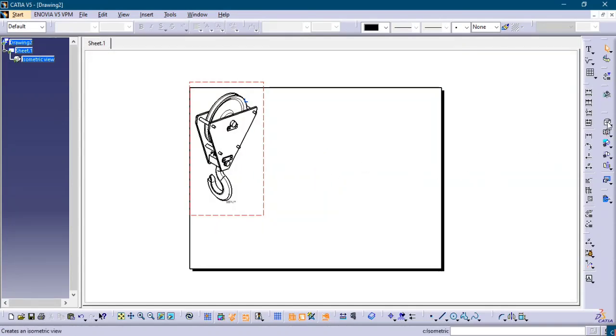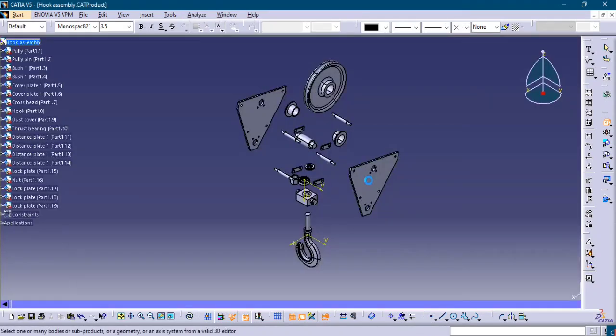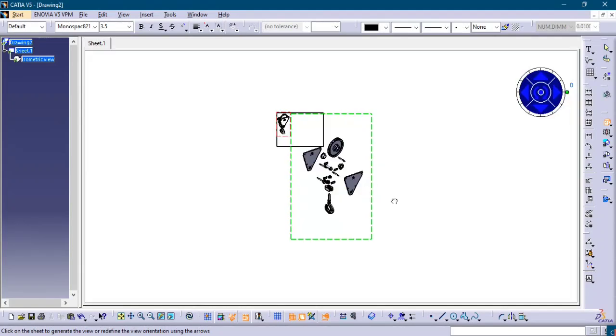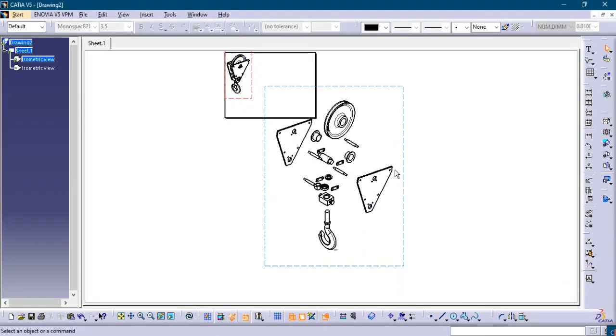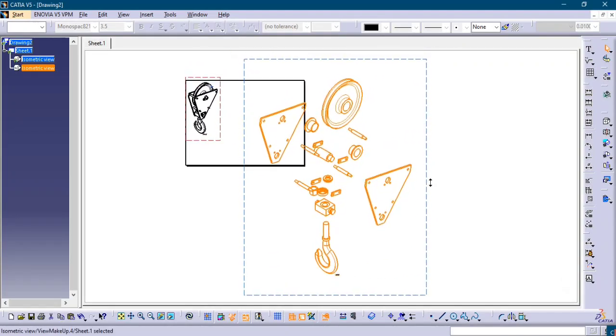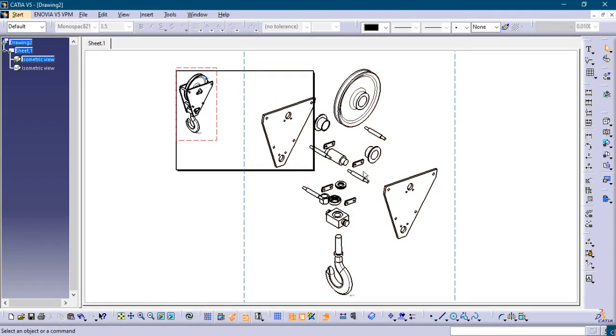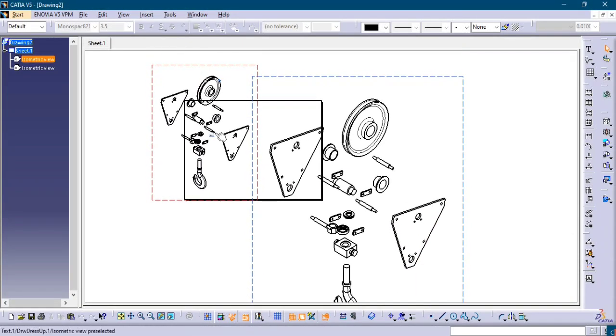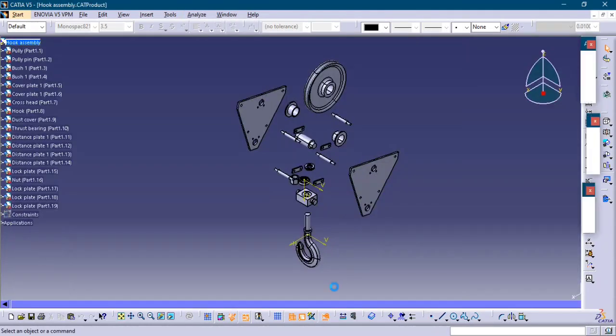The first thing is also disassembled. Now the update tool is there. Click on update, and again the things will be assembled. Now check on the drafting. What has happened? Here is also an updation. When you click on update, the things are assembled. But you want individual components. What do you have to do? For that, you need to add a scene in the designing environment.